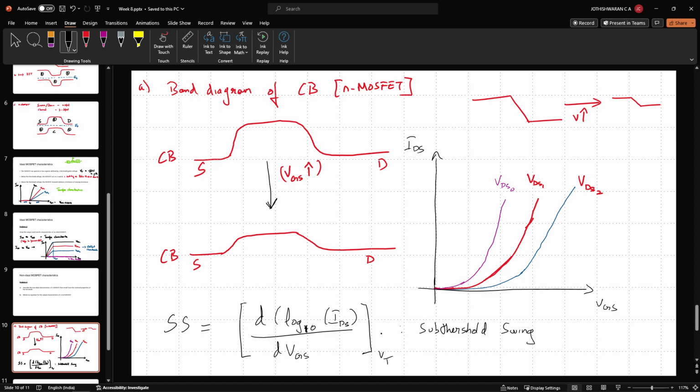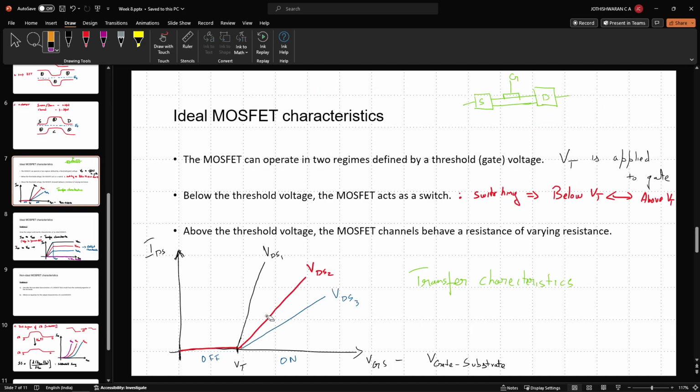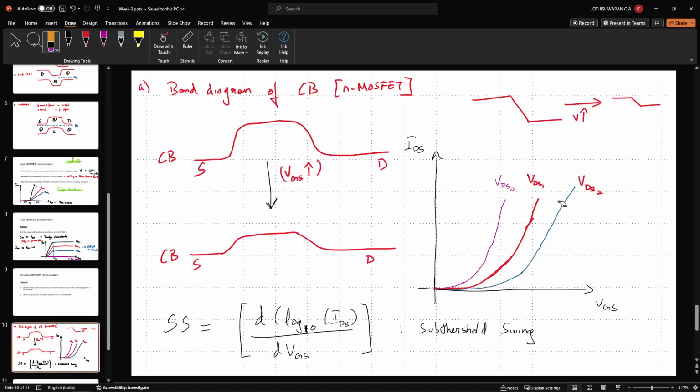Okay. So that value of VDS, I mean, I shouldn't say this is measured at Vt. The point at which this value goes above a certain threshold is what we fix as Vt. Because now we can no longer look at this kind of model and say there exists a single Vt. Since this whole behavior is very dynamic, I will have to find a point somewhere over here where the rate of increase really kicks up, identify that point, and then choose that as the threshold voltage for the system.